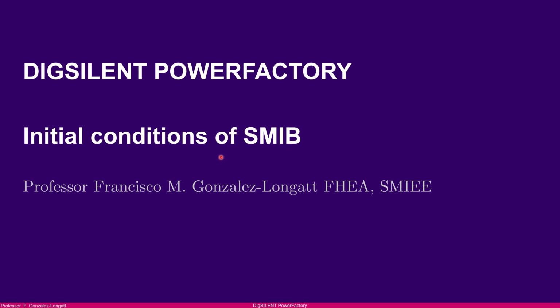Don't be confused. Initial conditions is very different to a classical load flow, okay? And that is especially true if you are working with DIgSILENT PowerFactory, okay? There is a module inside PowerFactory for calculating the load flow. That is the steady-state condition, okay? And then when you are working with the time domain simulation, there is a specific calculation function that is dedicated for calculating the initial conditions, okay?